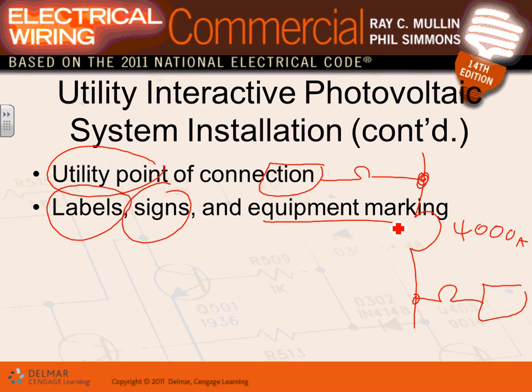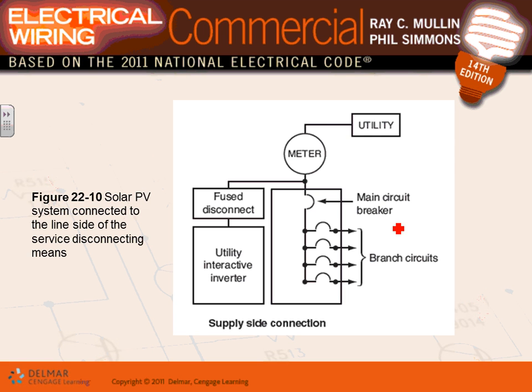If there's a fire in the building, firefighters pull in, they shut down the electrical power, but the solar photovoltaic system is still cooking, right? How are you going to shut it down? Even if you shut down the disconnect, guys, it's still generating. So you need to shut down the panel itself. So they created in 2014 a push button, you push it, and it de-energizes every panel. So it's really interesting to see how that goes.